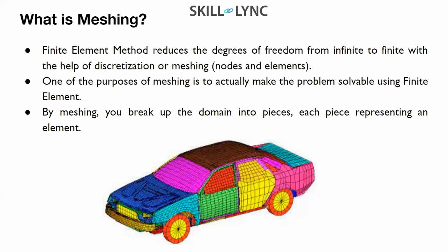As you have gone through in any mechanics book, the internal force is equal to negative of stiffness times x. The same thing applies here in the case of elements also, but the fact of the matter is that you are using the stiffness of an element, and that element has 2-3 nodes. Suppose you consider a 1D beam. In a 1D beam, you have that 1D element and it has, say, 2 nodes.